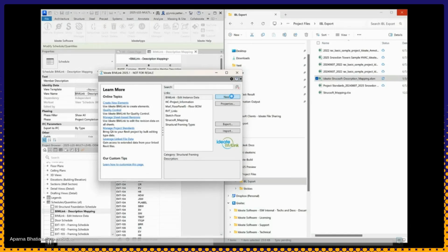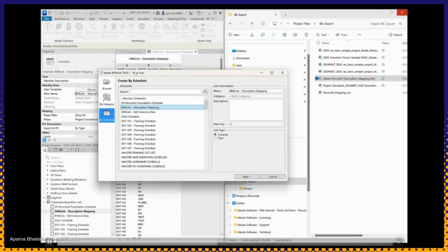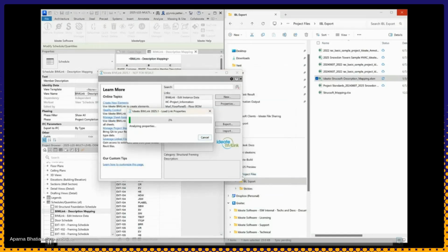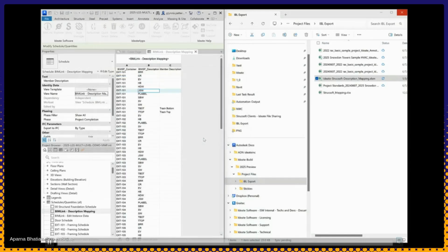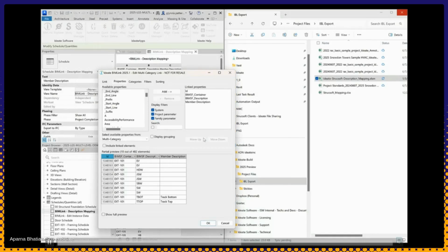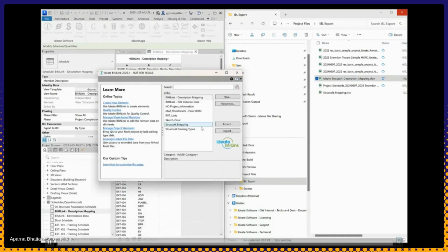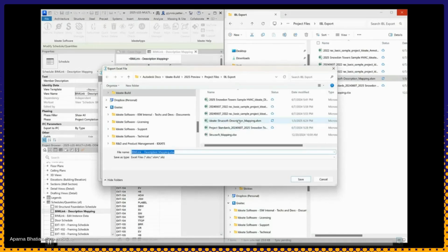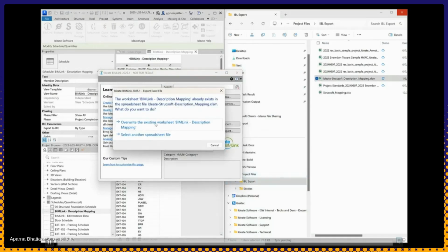The process is similar to what we did before. We'll use the new button, and we're going to use the existing schedule as our starting point for the data collection. We're looking at a list of quite a few elements, and you can see it tells you how many elements there are, and the preview shows you the first 10 of them. So we're going to write that data out. And of course, on the left in Revit, it's empty data, with 2 of the fields filled out.